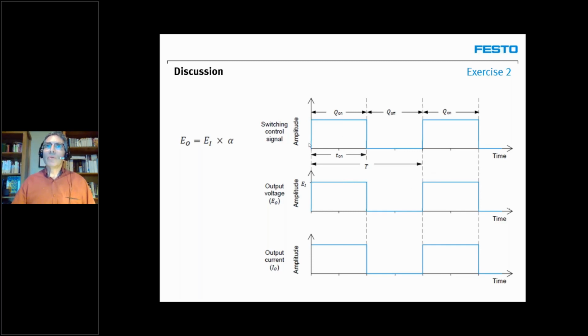So what will happen here is that by turning on and off our transistor really quickly like that, we will be able to change the average voltage reaching our resistor, because basically the resistor does not care too much about the fact that the voltage is constantly flowing or on and off if it switches quickly enough.